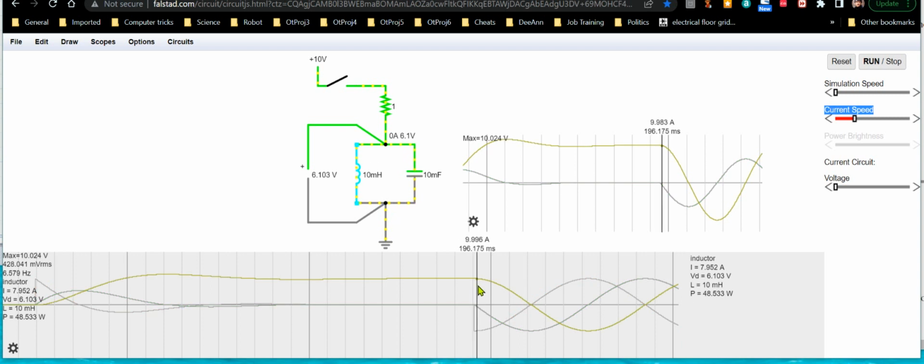So here, it's got a positive current flow, which it was trying to maintain, like it was over here. It's trying to maintain that positive current flow, but the only place for it to go now is in that capacitor, since I opened the switch. So basically that current is flowing into the capacitor, which is fine. Capacitors love that, because if they have zero energy in them, well, guess what? That's when they want maximum current.